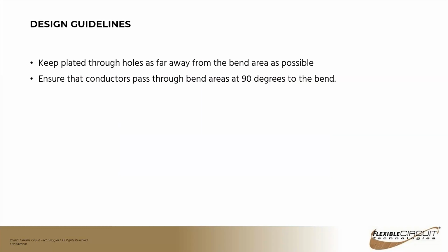So some additional design guidelines: keep plated through holes as far away from the bend area as possible. Any vias or plated through holes, try to push those away as far as you can. Ensure that conductors pass through the bend area at 90 degrees to the bend. So that's also important. You want to bend the conductors perpendicular to the bend itself.